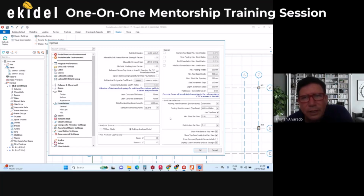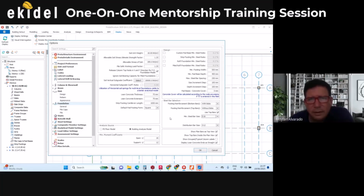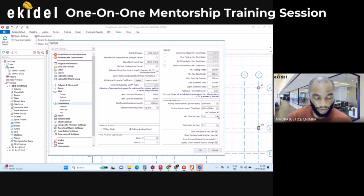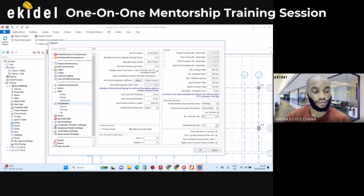So if you look at the last one that I sent you, it shows you the design for the pile. Okay. Because I think that one you sent me last was a pre-stressed pile, right? It's pre-stressed. That's what we do. But the thing is that we can use 5/8. That's what we usually use, no? 5/8, which is 16, I think, if I'm not mistaken. 16, yeah, 16 is a minimum actually, in my country too.